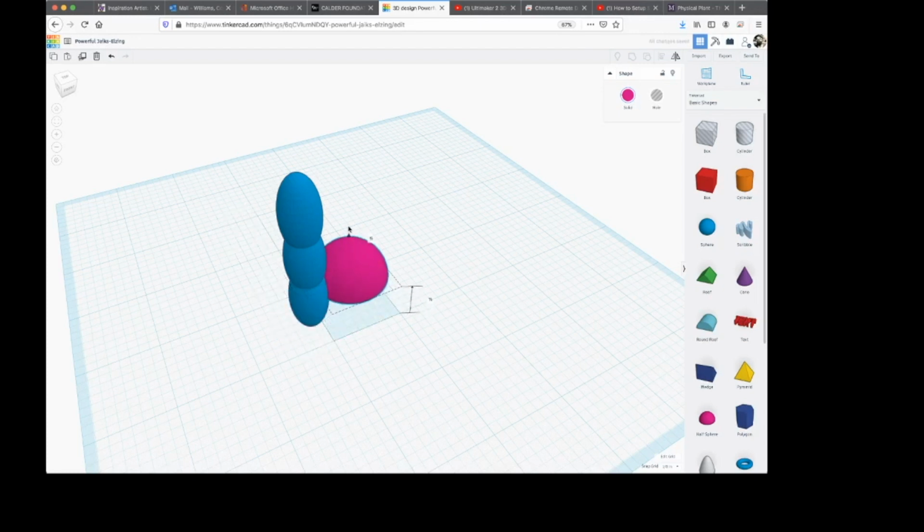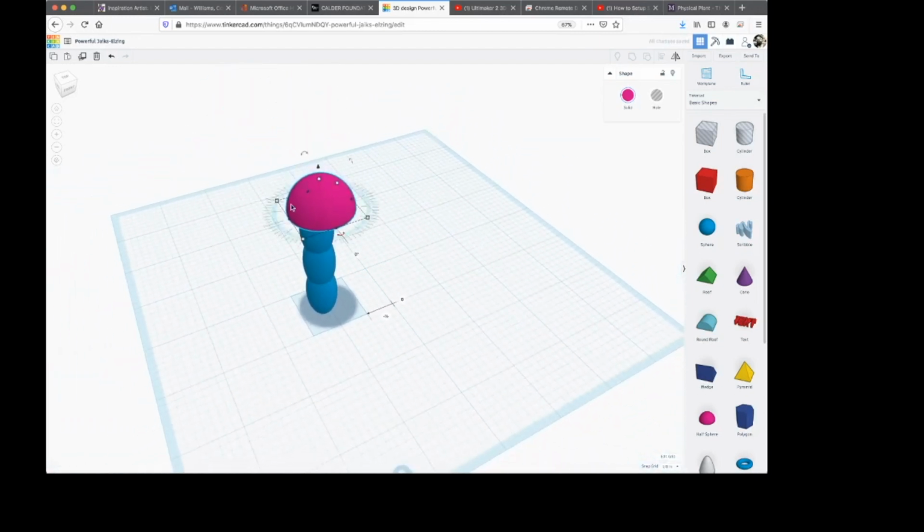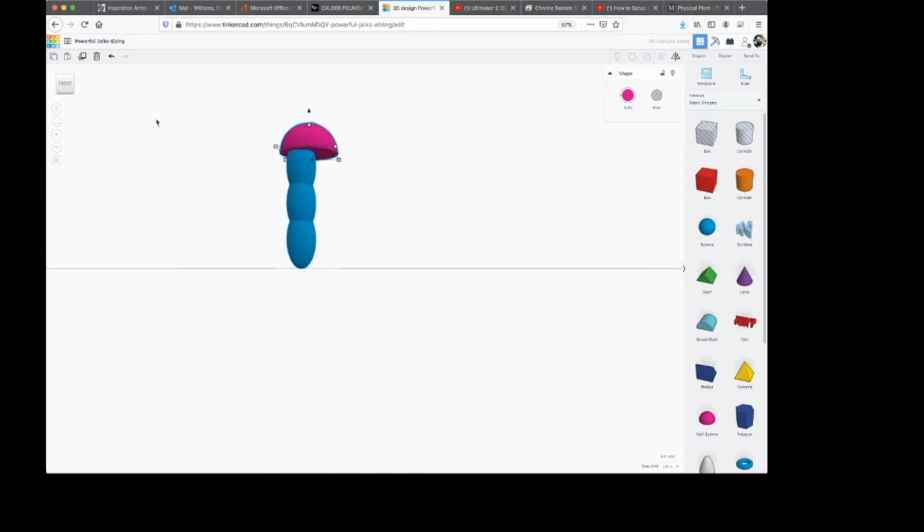Okay, and then grab the arrow on top of that half sphere, that hemisphere, and bring it up. Okay, so I could mess with that and get it in alignment. I went to using the navigation widget, I went to the front view. I could just kind of pull this back and forth and eventually get it into alignment. But the better way to accomplish that